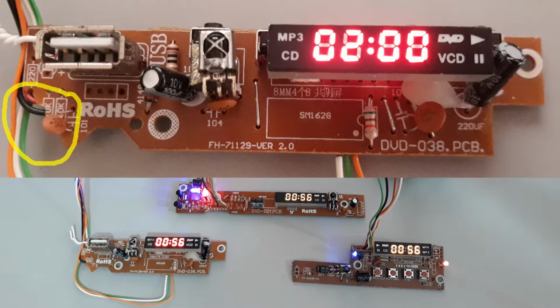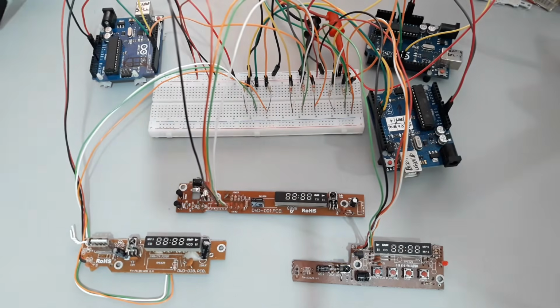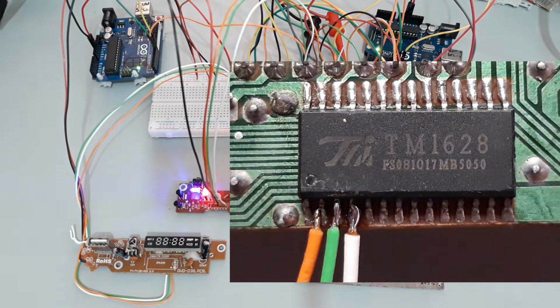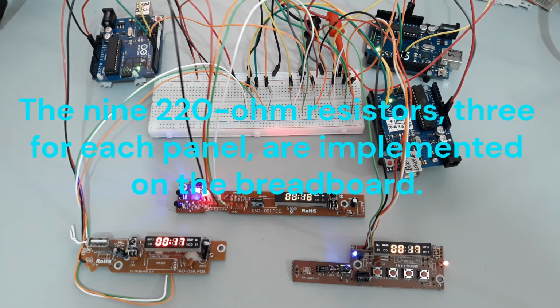I propose to show a panel that has a broken connector area on the PCB, a difficulty that was overcome by connecting the 3 pins directly to the driver pins. I'm not afraid to do it because, as you know, I always leave a resistor in series on each of the communication pins at the breadboard to avoid any wrong connection which can damage the Arduino.